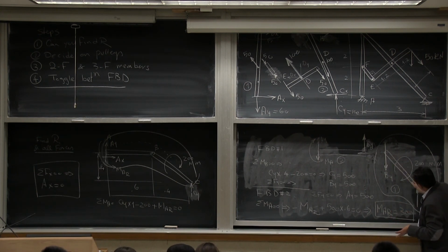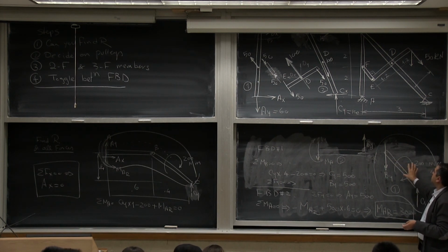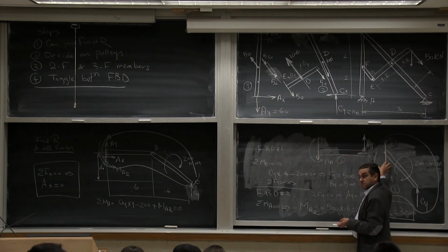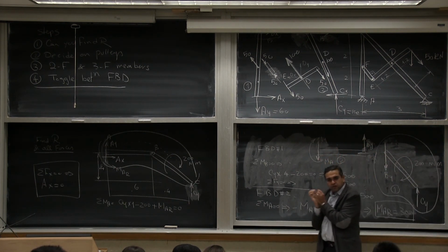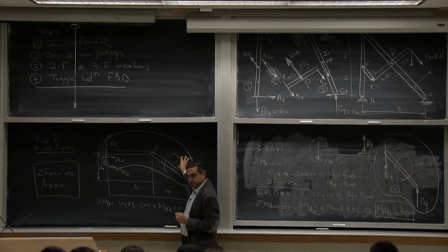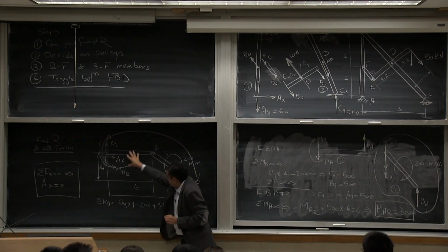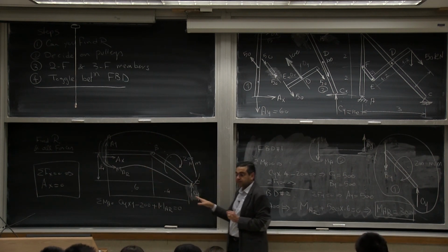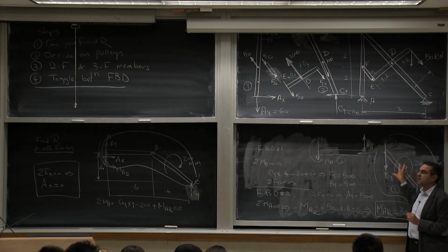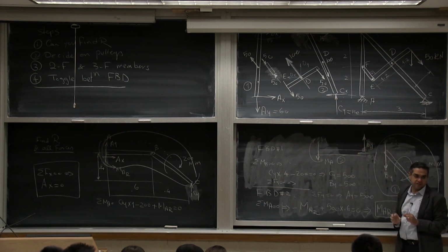And yes, you can move this up and down, but you cannot say, a couple is a couple anywhere, I'll put it here. This is a system, and this is a system. So everything is relevant. If you are looking at the external forces, this is part of this big system, it can move anywhere. Once you zoom in, you can move it within the system, but not between this system and that system.